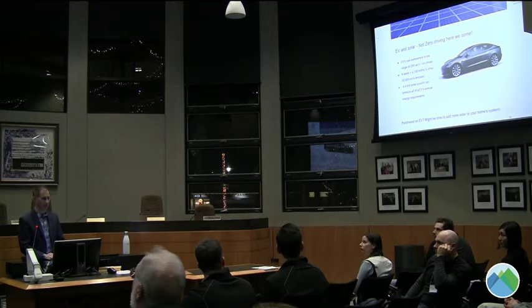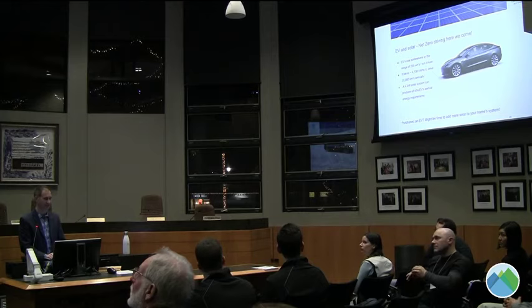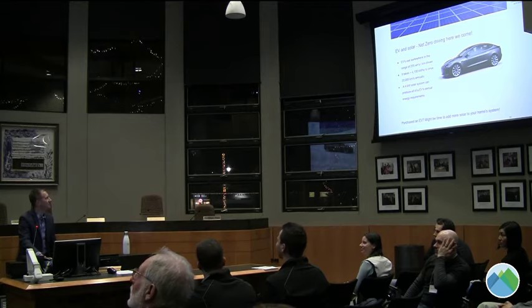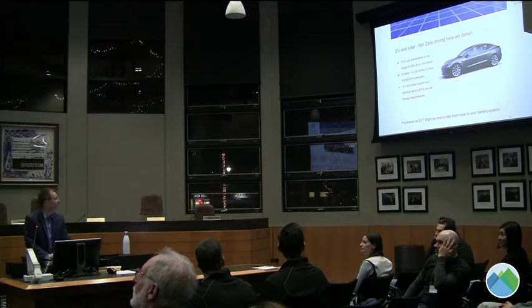Okay, EV and solar. So this is a beautiful solution, I think. Net zero driving, here we come. I Googled today because I don't have my Tesla yet, and it looks like they use about 205 watt hours per kilometer driven. That would convert to about 4,100 kilowatt hours over the course of a year, if you're driving 20,000 kilometers. That's actually not a lot of electricity.